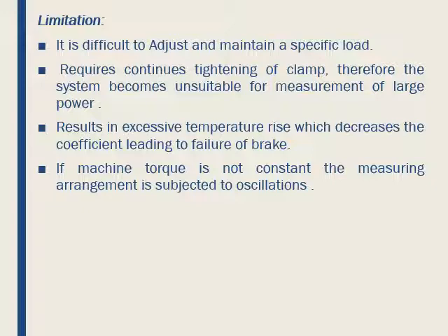Further, the use of the Prony brake results in excessive temperature rise, which results in a decrease in the coefficient of friction, leading to failure of the brakes. So in order to limit the temperature rise, cooling is required continuously. This is done by running water into the hollow channel of the flywheel.